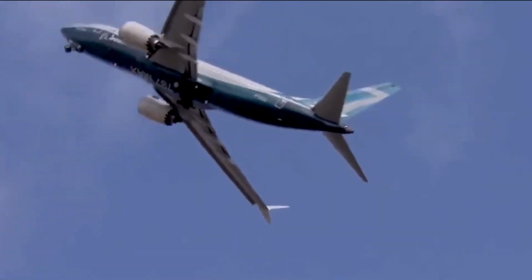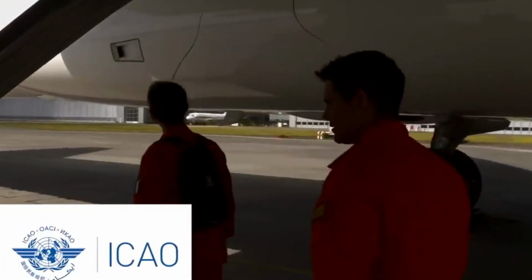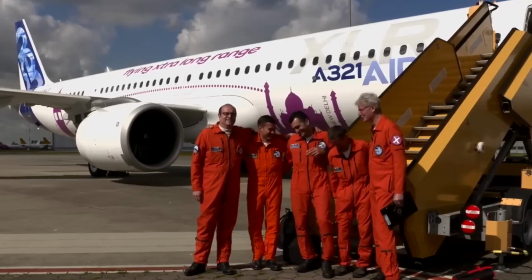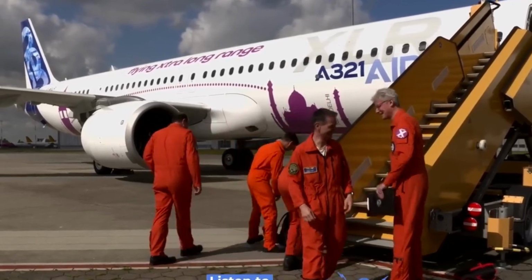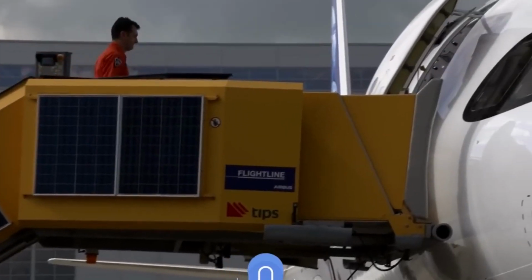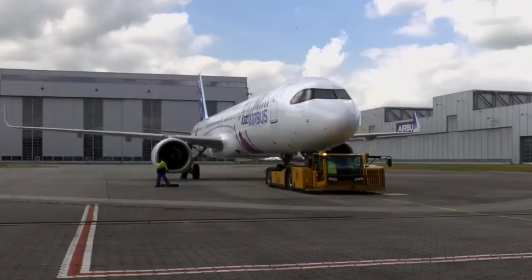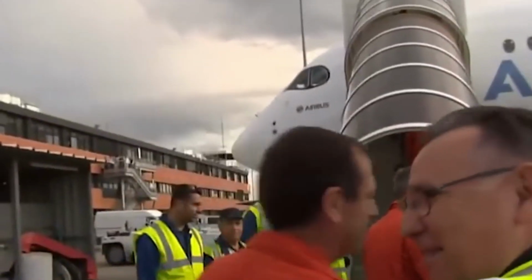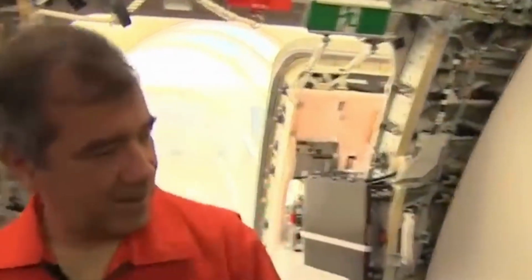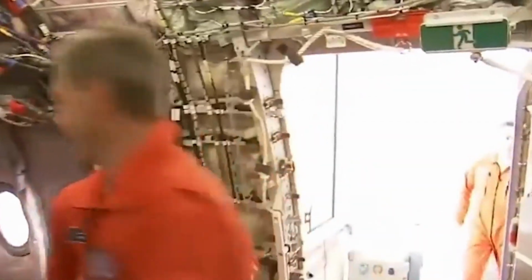Explanation of primary regulations, Parts 43 and 91. 14 CFR Part 43 Maintenance, Preventive Maintenance, Rebuilding, and Alteration. Section 43.1 Applicability. Paragraph A states quite clearly that aircraft, whether U.S. or foreign registered, operating under 14 CFR Part 121 or 135, and component parts thereof must be maintained in accordance with the rules set forth in this part. Although paragraph B states quite clearly the type of aircraft that this part does not apply to, it seems to have led to considerable confusion within the aviation industry.